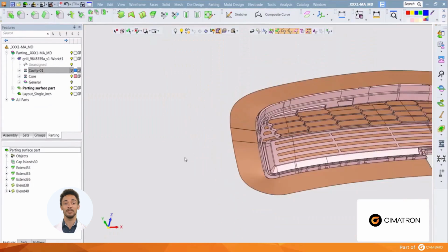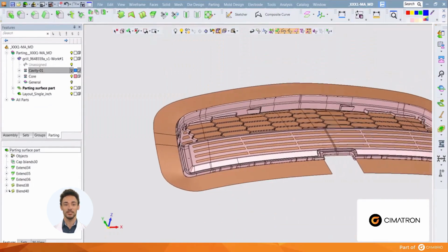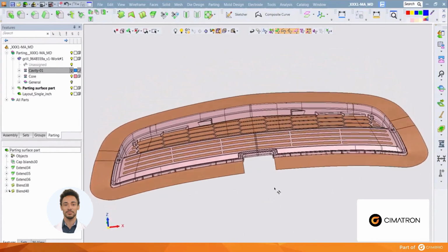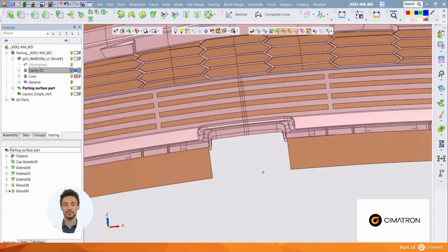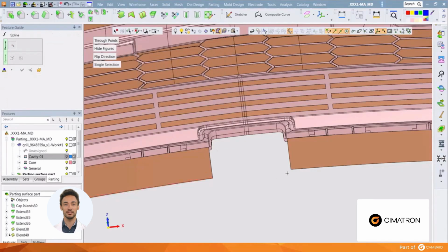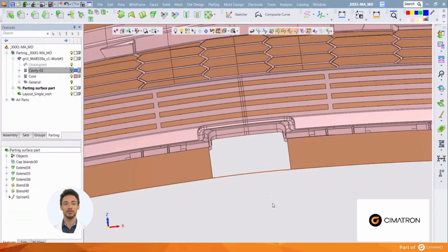We can now look at developing the surface in this U-shaped feature. There are many face functions we could use to fill this area. There are many curved edges and contour changes here. First, we'll create a spline from the two extended faces to match the contour.